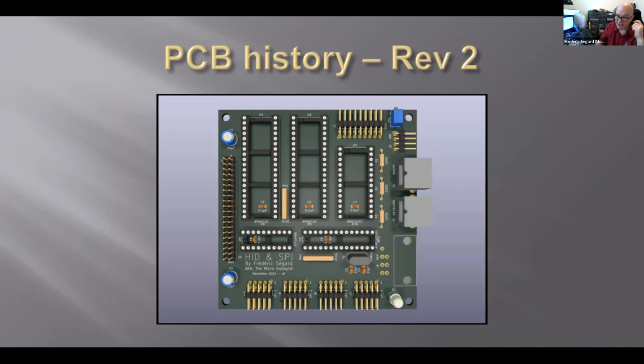Stack number 2 is the I/O, which has the PS2 and a NES controller and LCD connector, and the rest down at the bottom is the I/O for SPI, which I've never got to work because the footprint of the PCB was the wrong one.